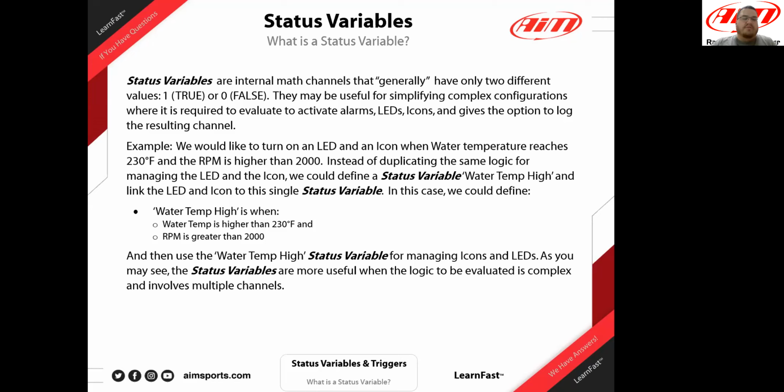And when those are true or false, we're going to get an ability to flag it, logging it even if we want to. And we have a small example here, where water temperature is higher than 230 and RPM is greater than 200. That's a simple one. That's really something most people will probably want to have. And there's obviously more complex ones, but starting simple, I like to do. The more you grow into the system, the more you might open other doors in your head for what else can I do? How else can I tie these all together? But a status variable, true or false, and we have the ability to flag it and log it as we want.